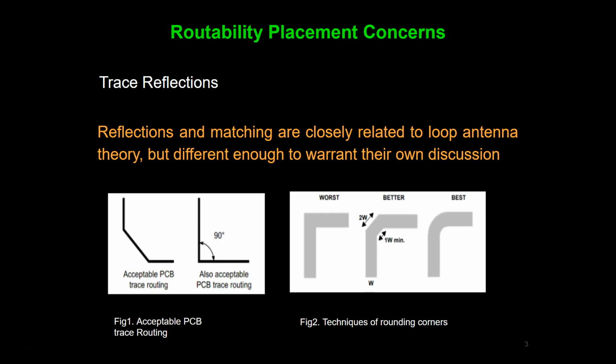If PCB traces turn at an acute angle, there is a higher possibility of an acid trap forming during etching on the inside of the angle. An acid trap causes over-etching, which can be a yield issue in PCBs with small trace width.